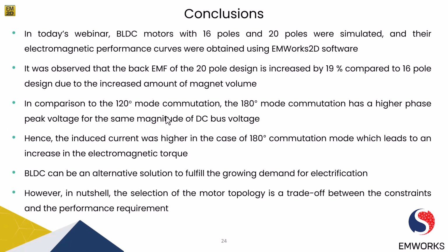So in today's webinar, we simulated a BLDC motor with 2 different configurations of slot-pole combination. One was 24 slots with 16 poles, and the second was 24 slots with 20 poles. We evaluated its electromagnetic performance and thermal performance, and finally we also had a comparison analysis using our EMWorks 2D software.